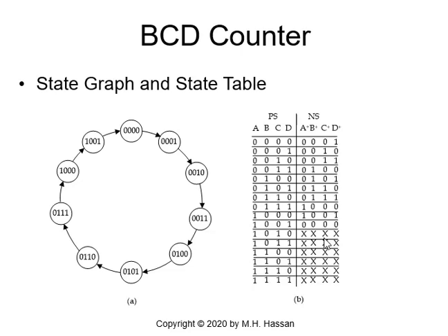But when you design with don't cares, you risk the possibility of generating another loop. If the counter enters another loop, a false loop, the counter will be a failure in the design.